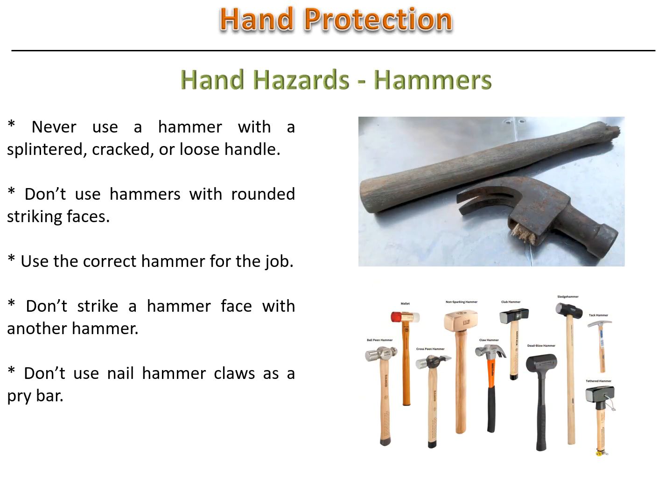Hand hazards: hammers. Never use a hammer with a splintered, cracked, or loose handle. Don't use hammers with rounded striking faces. Use the correct hammer for the job. Don't strike a hammer face with another hammer. Don't use nail hammer claws as a pry bar.